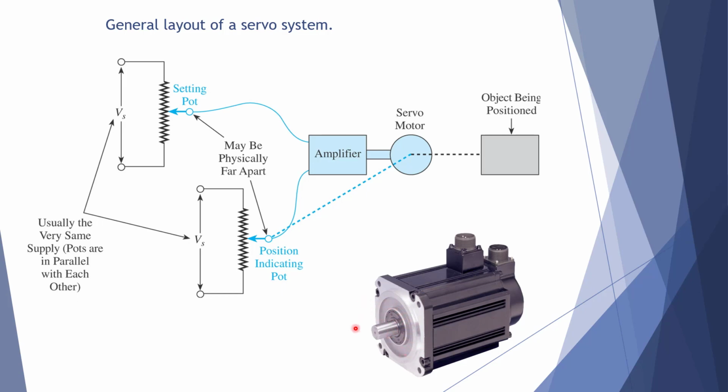And we talked about encoders, where I may want to rotate something a certain amount. Or even if I have a rack and pinion situation and I want to move in a linear direction, say from here to here, whatever that device might be, if I know the gearing, I know how much of a rotation needs to occur to get that amount of linear motion.